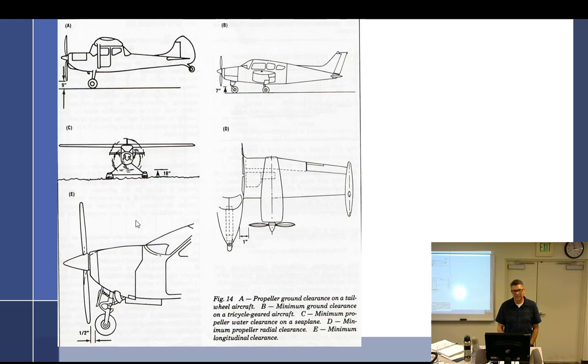What do you mean by dressing? You take a file and clean up any nicks and dings. If you took it off to dress it, would that then be a prop strike? Yeah, technically, I don't know. You're kind of splitting hairs there.